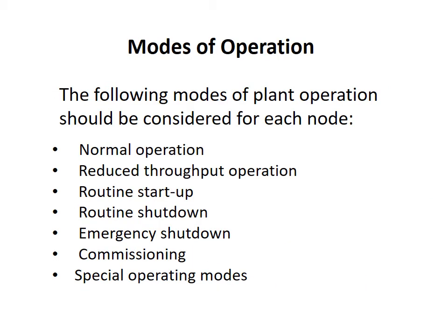Modes of operation. The following modes of plant operation should be considered for each node: normal operation, reduced throughput operation, routine startup, routine shutdown, emergency shutdown, commissioning, and special operating mode.